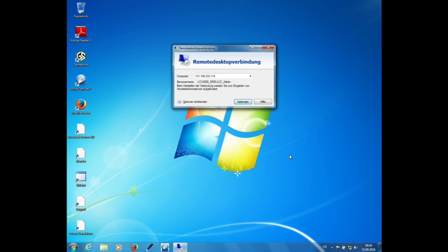If you want an actual accurate vacuum reading, you need a quadrupole mass spectrometer, a residual gas analyzer, that would give you an absolute measurement. Apart from that, it's always a relative measurement where you look at whether it changes or doesn't change.